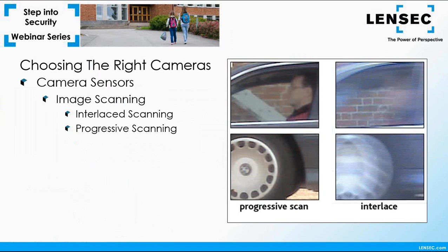With the progressive scan image sensor, values are obtained for each pixel on the sensor. Each line of image data is scanned sequentially, producing a full frame image. In other words, captured images are not split into separate fields as with interlace scanning. With the progressive scan, each line of the image is sent one at a time in order. Moving objects look better on the computer screen using the progressive scan technique. You can see that here on the left of our example.